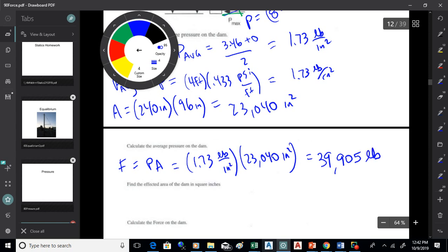So when you build these dams, there's a lot of force trying to push them down the river. They have to be anchored into the walls of the river, into the banks, and also down at the bed of the river too. So they put extra walls on the dams to embed them. Also, the pressure builds up behind the dam and pushes the water under and around the dam. It's called piping. And so, of course, you want to be sure your dam's functioning properly.